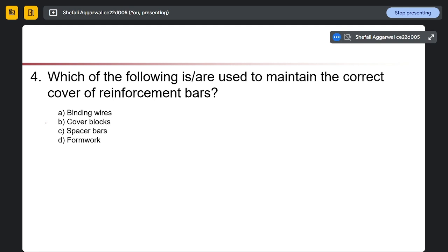Here is a typical composition of different types of mineral additions. If we talk about normal Portland cement, we have almost 65% calcium oxide, 20% silicon oxide, and 2 to 5% aluminum and iron oxide. If we are using other admixtures, how these compound values will change is shown here in the typical composition.